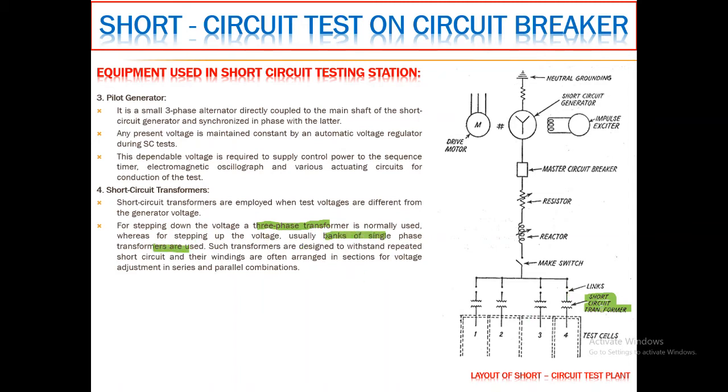Again, the design of the short circuit transformer is completely different from the conventional transformer. They are designed to withstand repeated short circuits, and their windings are often arranged in sections for voltage adjustment in series and parallel combinations.